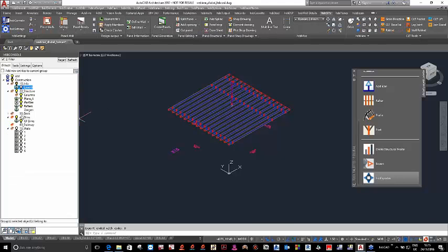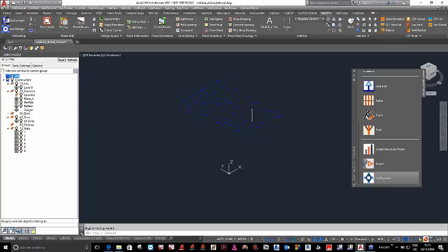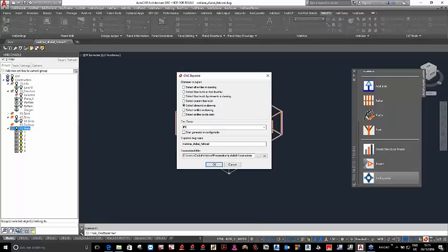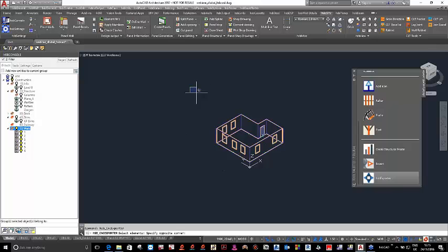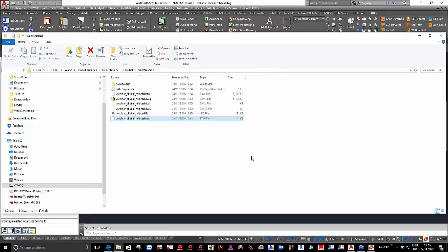Following that, I'm going to create the same file for the walls. My mistake, it's not the same file, it's an IFC file, which for the walls works better. So I'm going to create from this icon, IFC, select all the panels, now if you go back to the folder, that file has been created.